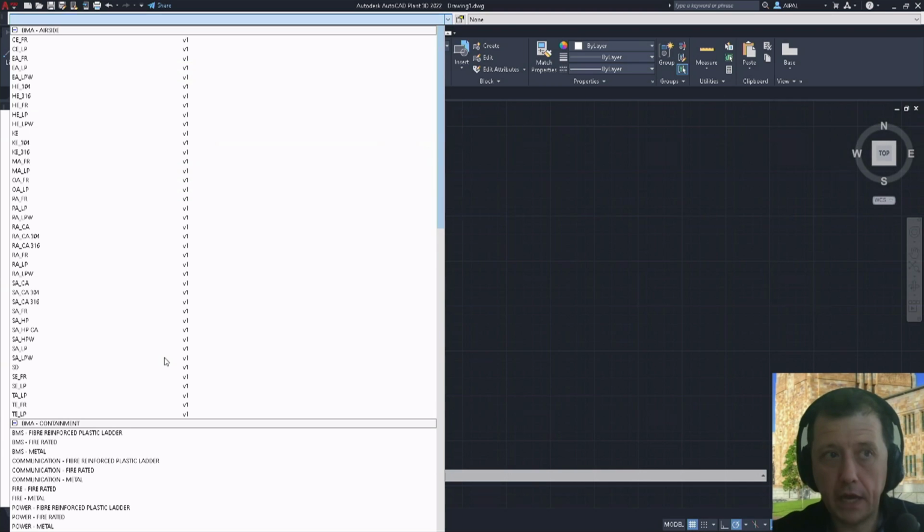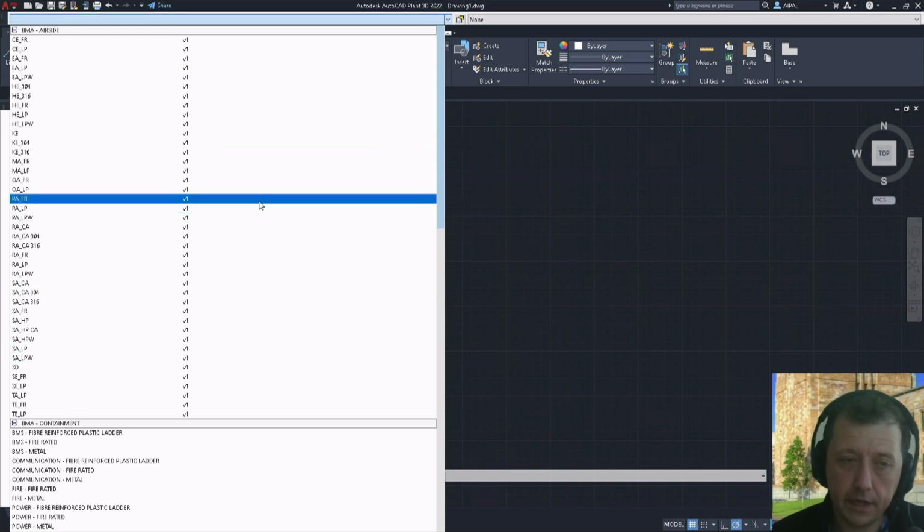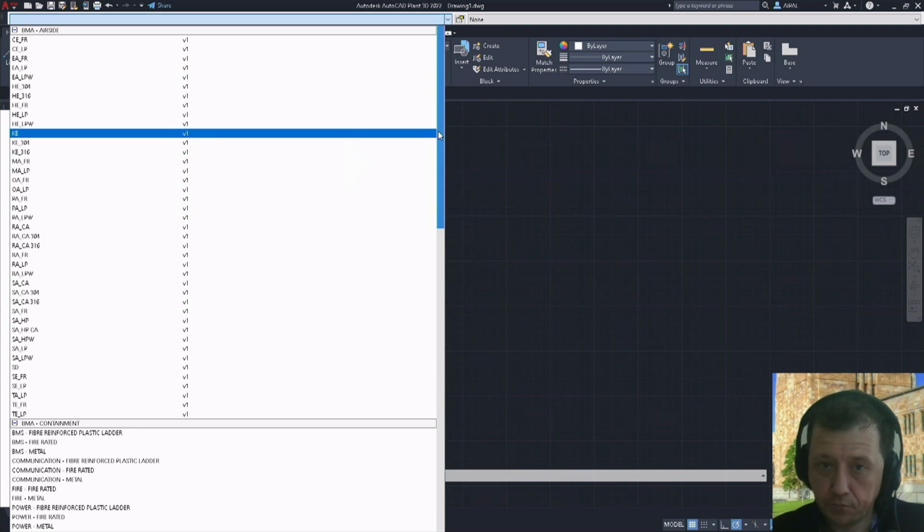Fabrication parts in Revit are not a Revit family that you create by adding reference planes and 3D geometry. The fabrication parts are created and controlled, or the database is controlled, here in one of the fabrication tools. So you cannot modify the database in Revit. You can only edit the parts, like the few dimensions that I showed you here. But really to set up the database, you would need to have one of these fabrication tools.